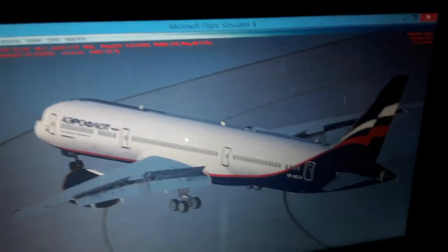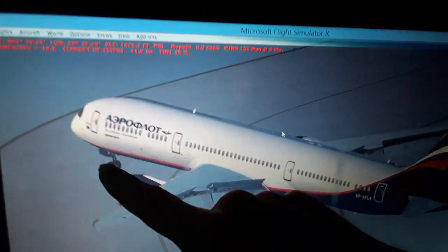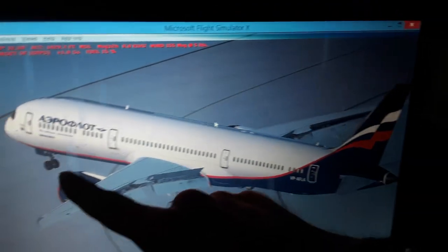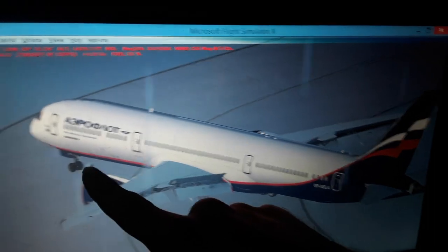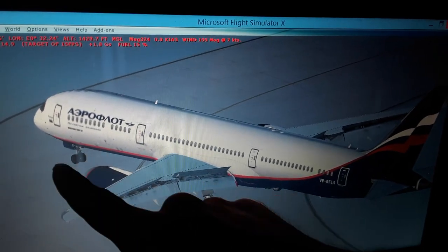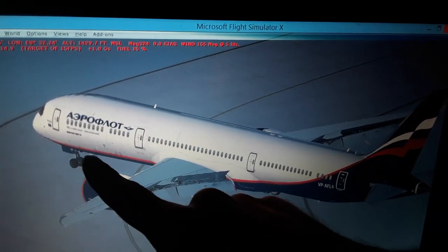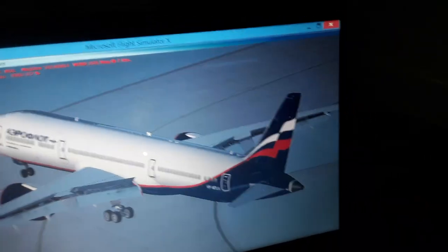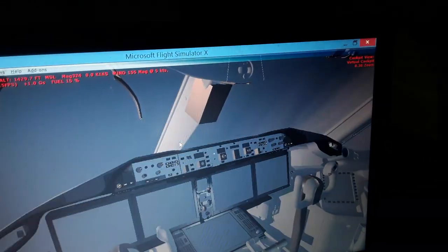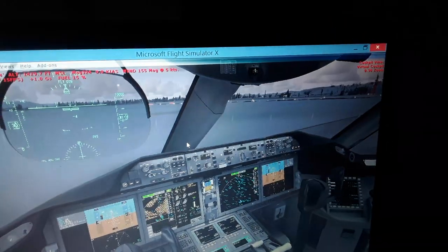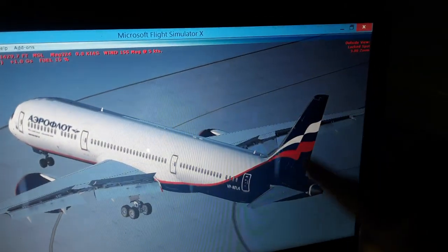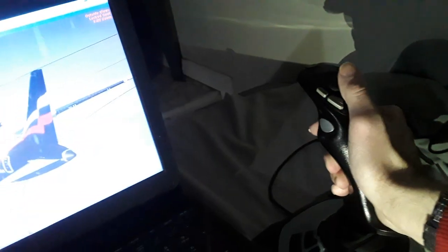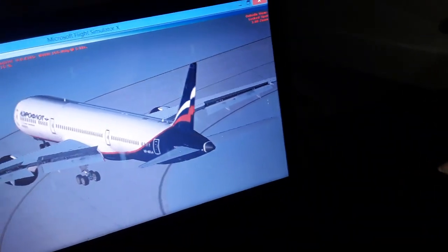So you see the rudder pedals act to control the rudder function left and right, the yawing axis. Also we have, from 0 knots, the nose wheel steering of the front nose wheel. We can deflect the nose wheel automatically from the computer from 0 to 76 degrees with the left and right deflection. As we accelerate for takeoff, we increase the airspeed above 45 knots. The rudder becomes aerodynamically effective a lot more.